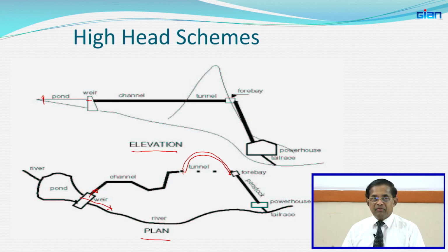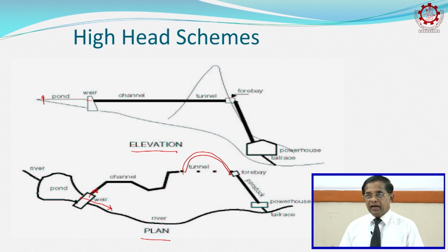There are many subcontractors and service providers where if you ask them, they will come and have the tunnel done. And also these hills are very rocky, suitable for tunnel building, not like loose soil, right. So they are both advantages. So in those countries, even for mini hydro, they use this kind of a tunnel rather than using a canal, right.